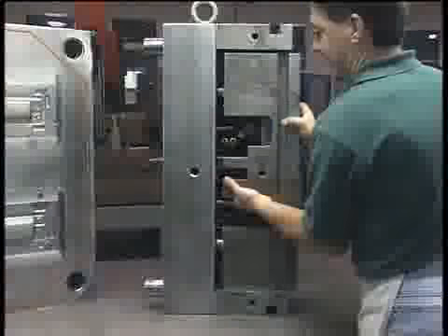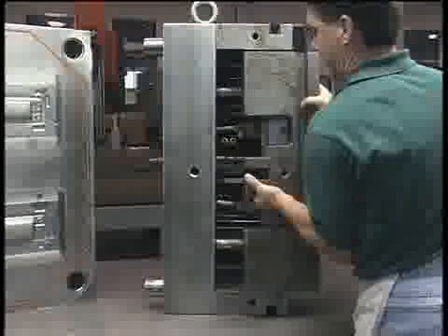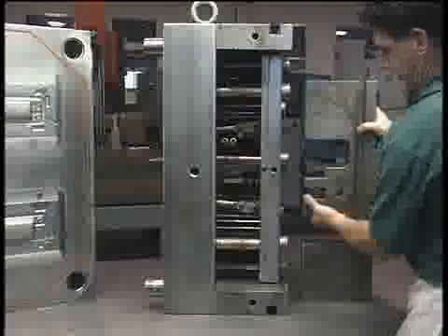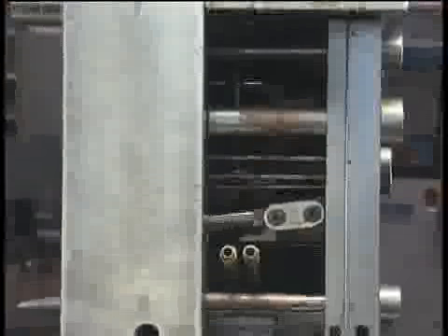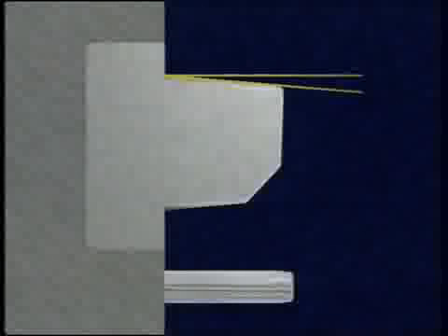An ejector system is required to release the casting. In the system, ejector pins are mounted between ejector plates in a pocket on the ejector side of the die. In most cases, they are activated by pneumatic or hydraulic cylinders. To facilitate casting ejection, dies and cores incorporate a slight draft or taper, the amount depending on the metal to be cast. In general, the lower the metal's melting temperature, the less the draft required.